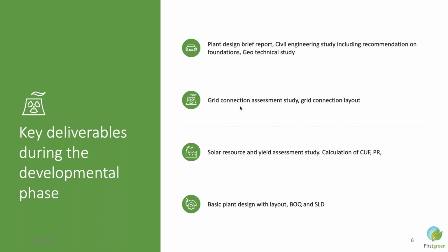At the end of this phase, you will also have your plant brief design. You have also finalized your typical configuration of your project, what type of inverter, what type of modules will be required, how many modules in a single string. So all these things you will keep adding to your layout, what way you will install the plant, where will be the road, where will be the drainage, how the land will be utilized in best way, where from the transmission line will pass from the land.